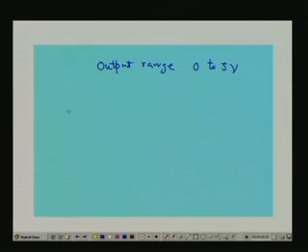And we need, basically, one Wheatstone bridge along with an instrumentation amplifier. The Wheatstone bridge is necessary to give an output of 0 volt at 75 degree centigrade, and the output of the Wheatstone bridge will be very small, and hence an instrumentation amplifier is necessary. Now, we have proposed the following circuit, right.